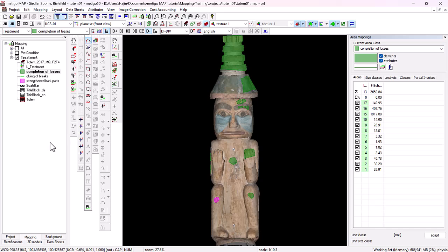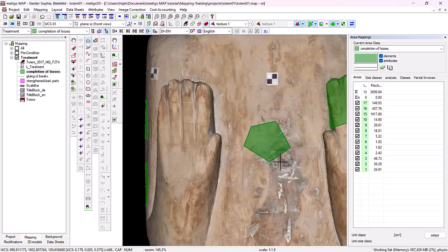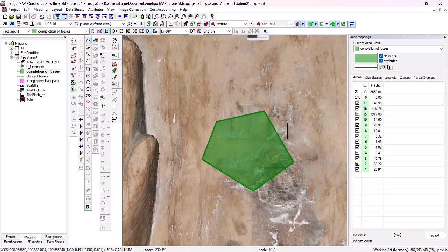That is, if I want to expand or shrink areas now, then we have the option of the auto mode, which we already know from 2D mapping. That means I choose the auto mode in the fourth column, select it and have the option plus and minus. That is, if I choose the plus and take the command spline, then I can draw a new surface, a new contour.